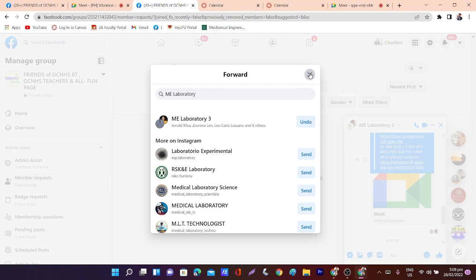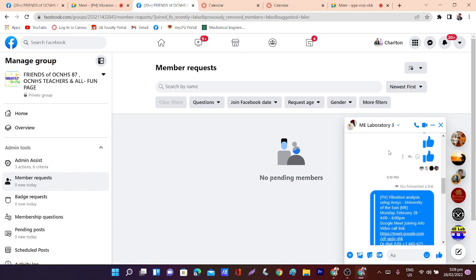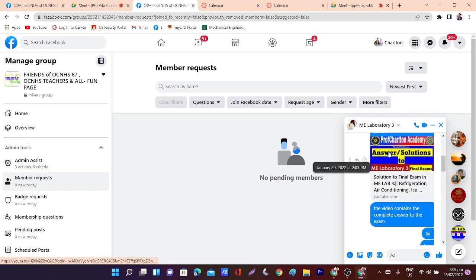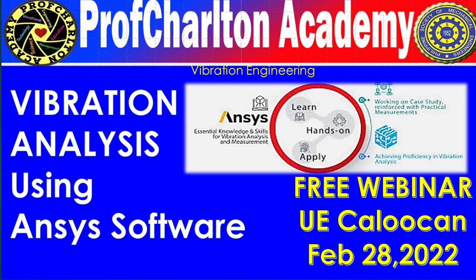So there are also some risks and limitations with additive manufacturing. One of the issues that's common in additive manufacturing is build failure. Build failure means when you print the part, especially metal, after printing you may see some crack formation or deformation of the shape. So instead of your required design, you will get a slightly deformed part after printing. These are the common issues that people face during additive manufacturing.